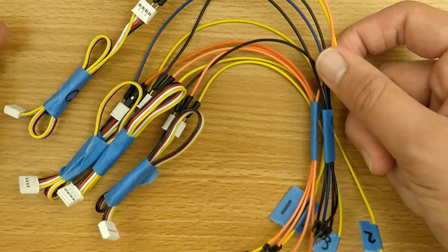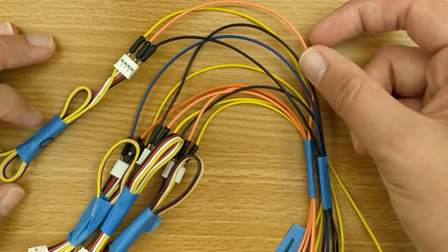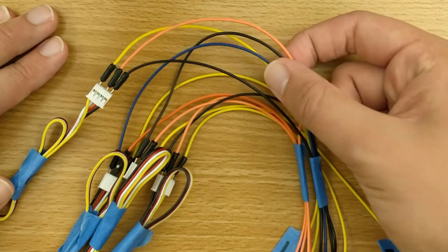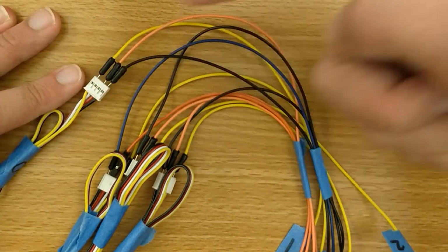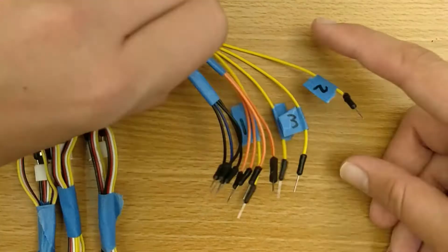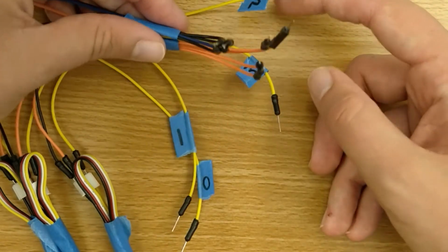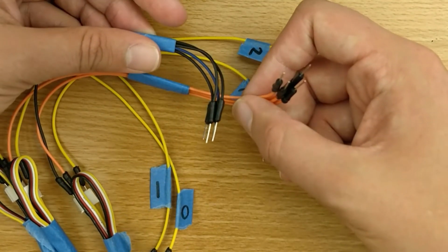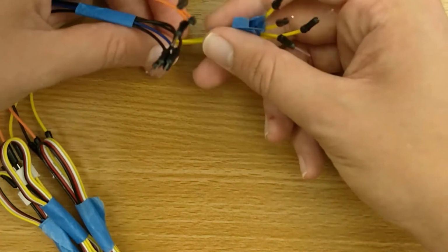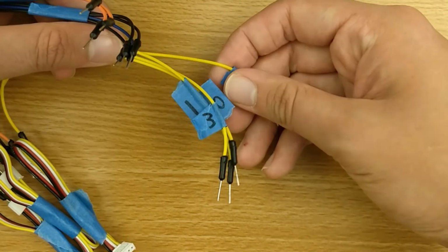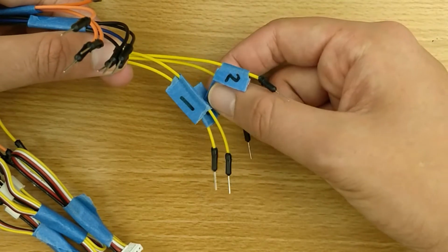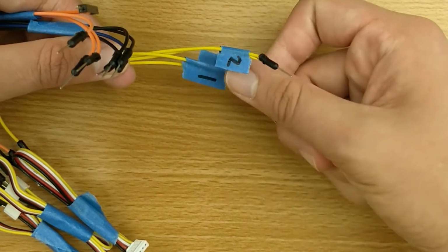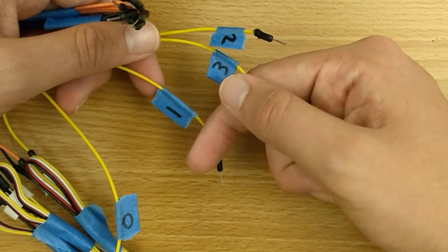I've tried to match colors roughly. All of the reds are plugged into oranges. You see we have a blue ground wire here instead of a black, but all the yellows are connected to yellow Grove wires, oranges are to reds, and the blacks and the blues are to blacks. On the other end here, I've taped things together based on what color they are and not what Grove connector they're hooked up to. And these here are the wires that let us actually control the relays. I don't have them taped together, but instead you can see I have the number that they're supposed to be plugged into taped on here, so 0 should go in D0, 1 goes in D1, etc. I have 2 other male-to-male wires here, just for later.